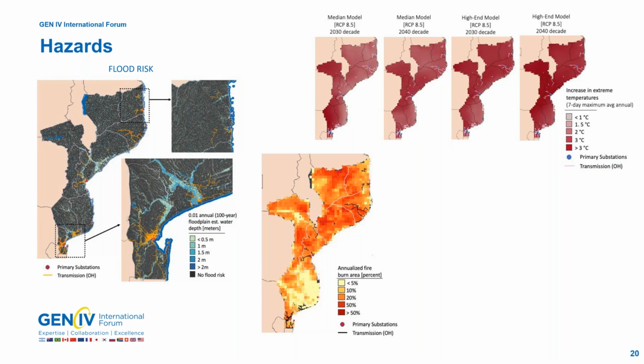Another thing in power systems that's affected by extreme heat is the efficiency of transformers. It also goes down as the temperature increases, and more importantly, the lifetimes of the transformers decrease. So if you're designing or expecting the design of a transformer to take you 30 years, it's not unreasonable for that to drop by as much as a third if you're operating those transformers under extreme heat conditions. And so that's something that has to be built into the system design because you're going to have to factor that into the operation and maintenance costs, or you should factor it in.